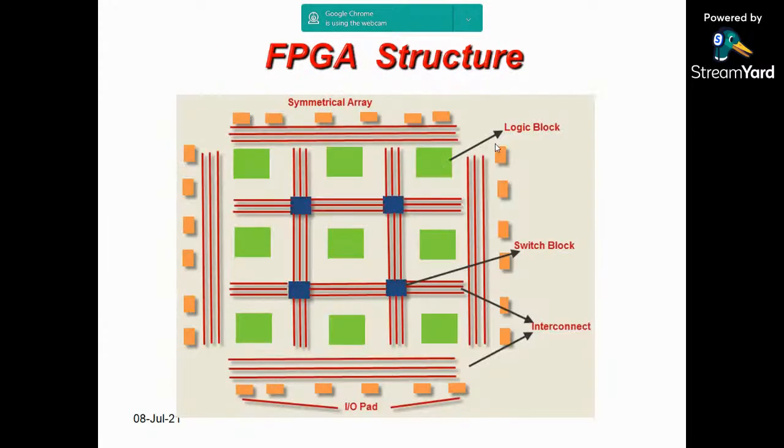Okay, I just want to show how the structure of an FPGA looks. You have a green color, right? All of these are the logic blocks, or configurable logic blocks. That means you can configure them anytime. And you have an interconnection switch matrix, a programmable interconnection matrix, flowing in between. Okay, interconnects. So you can realize any function in an FPGA.